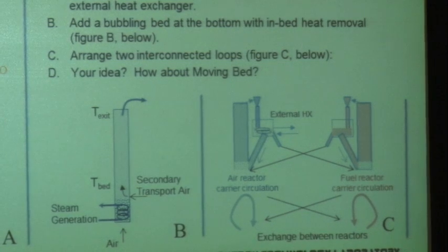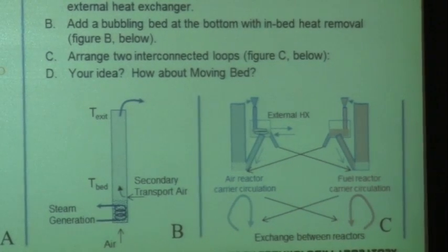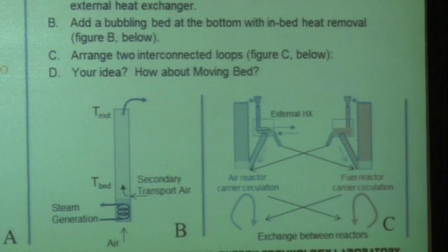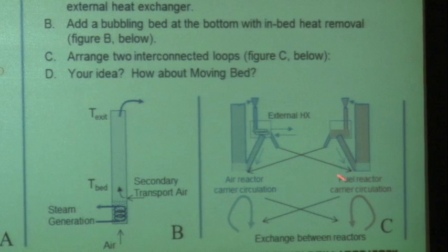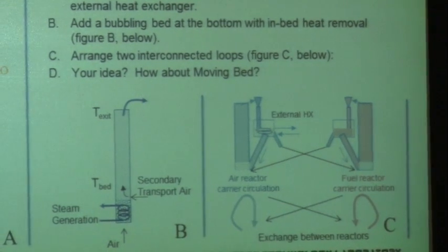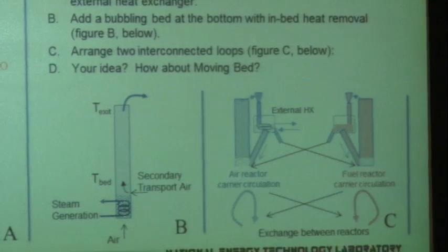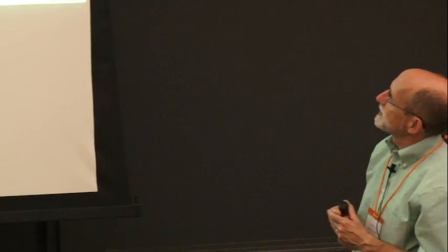So the advantage here is you get as much residence time as you need, within reason, going around these loops, right? And you take off just what you can afford to go over the reactor. The disadvantage is you have a lot of circulation going around each of those loops many, many times, potentially 4 or 5, 6 times. But it gets you out of the problem of I didn't get enough conversion, I can't balance my thermal with my hydrodynamics. So you start to understand there's quite a few trade-offs when you want to put one of these things together.